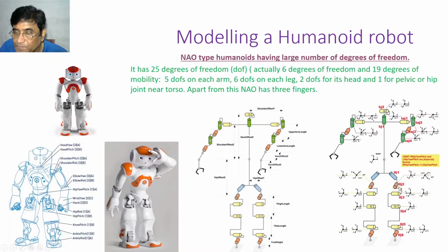To reduce unnecessary parameters and to capture the rotation correctly, this kind of coordinate frame attachment is done. This is known to you, so that their origin will remain the same, and only one will rotate about another, all kind of thing. As far as possible, we will continue and we will show you that as far as possible we want the Denavit-Hartenberg parameters to be 0.